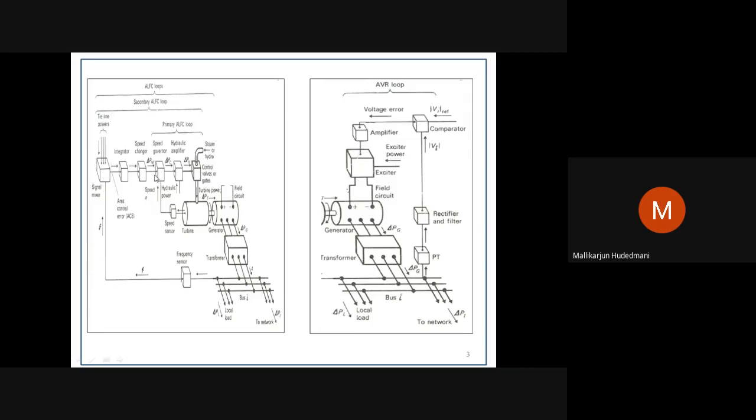What power this generator is transacting and what line frequency it is having, this is transformed into an area control error. This area control error is nothing but an input to the integral block. This integral block, the integral controller, the PI controller, will magnify the error, apply a gain of KI, the integral gain, amplify it and accumulate it as an integration and set it as a speed changer point. Set it to either reduce or increase the speed set point.